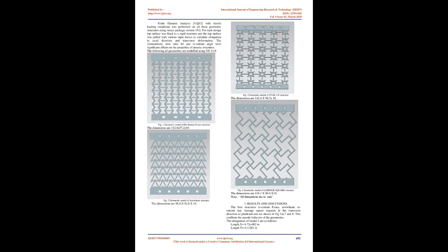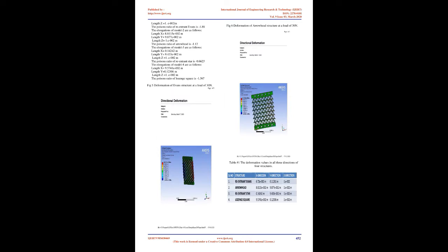When a material is stretched, there is normally an accompanying reduction in width. A measure of this dimensional change can be identified by Poisson's ratio, v equals lateral strain over longitudinal strain, where longitudinal strain and lateral strain mean strain in the longitudinal direction and strain in the lateral direction when the material is compressed or stretched in the axial direction. Auxetic structures are those with a negative Poisson's ratio and display the unexpected property of lateral expansion when stretched, as well as equal and opposing densification when compressed.